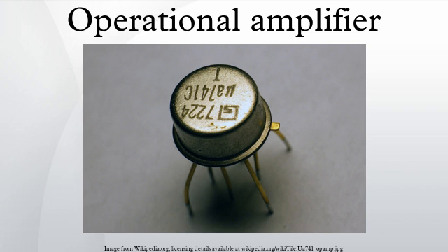This portion of the op-amp cleverly changes a differential signal at the op-amp inputs to a single-ended signal at the base of Q15, and in a way that avoids wastefully discarding the signal in either leg. To see how, notice that a small negative change in voltage at the inverting input drives it out of conduction, and this incremental decrease in current passes directly from Q4 collector to its emitter, resulting in a decrease in base drive for Q15.